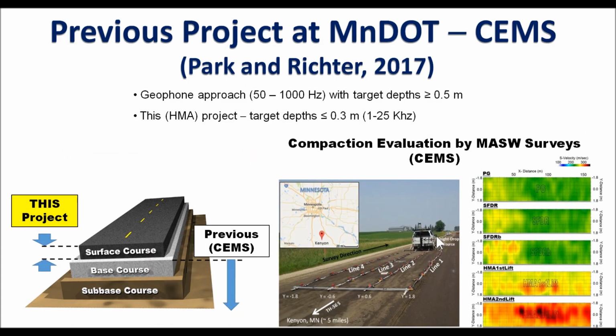There are many MASW projects previously executed at MnDOT during the last about 10 years, and the most recent one is called SAMS, Compaction Evaluation by MASW Surveys, and results were presented in Park and Richter 2017. It basically dealt with the evaluation of shear wave velocities right below this top pavement layer down to about 1 meter depth. So it dealt with this base and subgrade layers in terms of shear wave velocity evaluation.